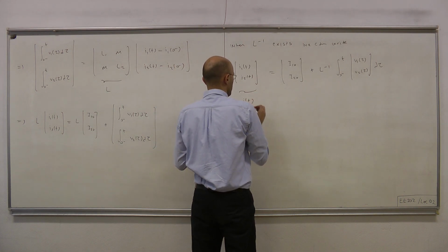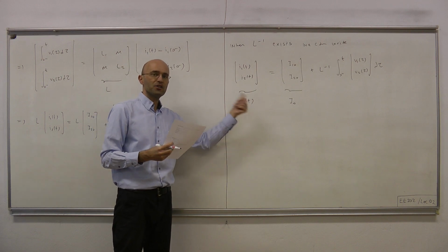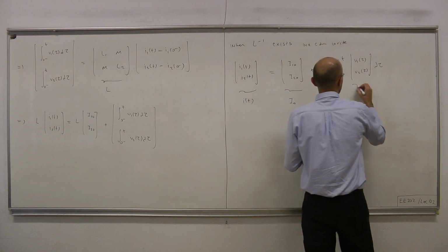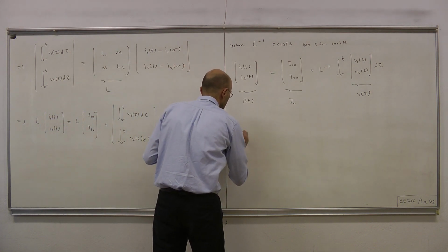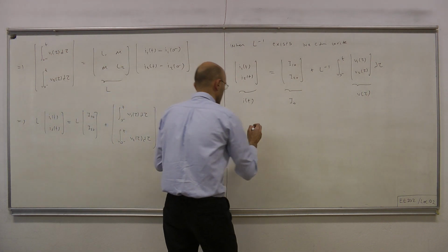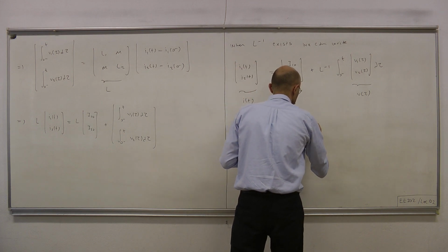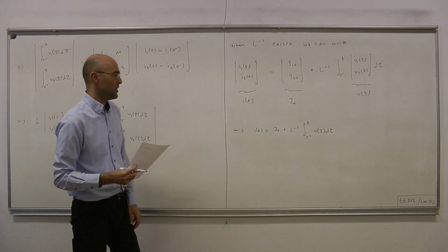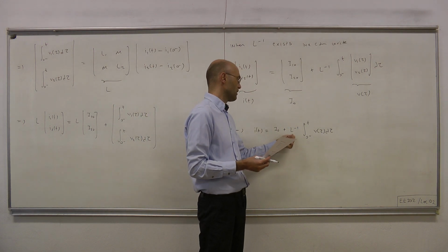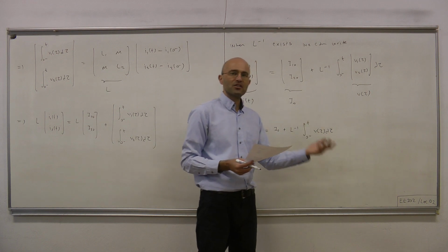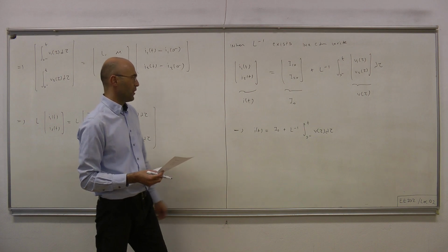So this is I of t, our inductor current vector. This is I0, or I of 0 minus, which is our initial current vector. And then this vector here is V of tau, the voltage vector for the coupled inductor. Okay. Therefore, we can write this equation in more compact form and say I of t equals I0 plus L inverse times the integral from 0 minus to t of V of tau d tau. Okay. This is the same form as the terminal equation for a single inductor. The only difference is that with a single inductor we usually wrote this term as 1 over L, but now we cannot, because 1 over L doesn't make sense, since L is a matrix, no longer a scalar. Okay, so this is the terminal equation in integral form.